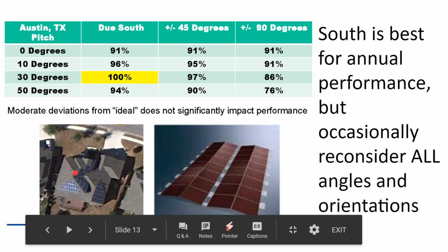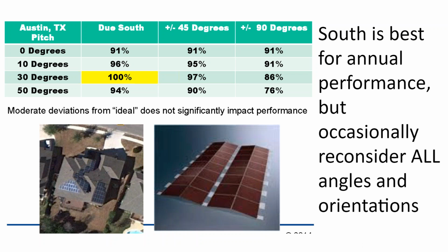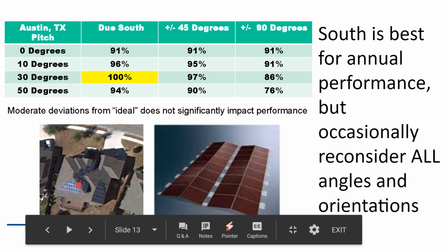And so, actually, there's economies of scale that say, well, maybe we do a larger project and we cover the less ideal surfaces, but even though they'll produce 15% less, maybe by doing a larger project, we get more than a 15% discount on our installation pricing. And so a large project that is off ideal can be more cost effective than a small project that only faces ideal. Because, of course, only one of the 4 orientations of your roof surface is going to face south.